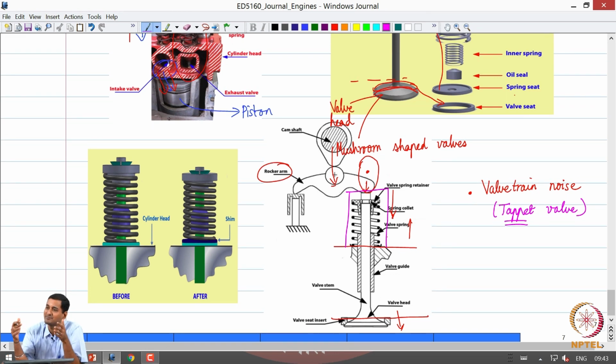See, this is like a mass spring damper system, right. You have inertia, that is why you can't close instantaneously. So, you have a return spring. So, what people do is that they introduce a damper, and as we know from our basic dynamic systems also, if you put a damper and you increase the damping ratio, the oscillations will be subdued, right. So that is what people do by putting a tappet.